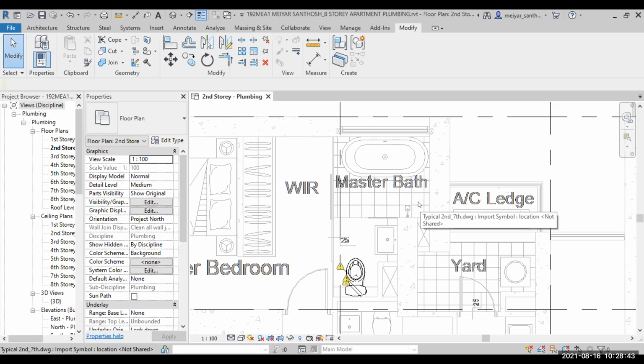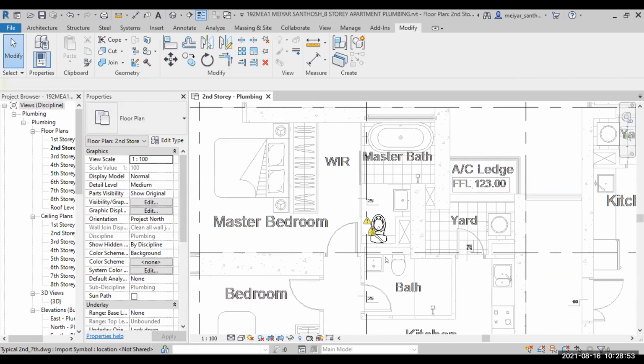Then this one also, you should have a floor trap somewhere, I would say this area here. So total 1, 2, 3, 4. Then one floor trap normally hidden somewhere behind. Here should have an opening outlet for your drain pipe, for the washing machine to plug into. Then whatever water flows will go to here and go down.